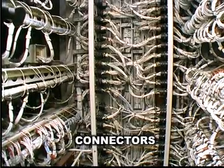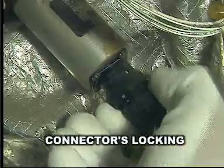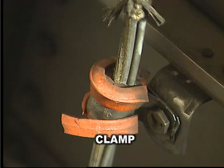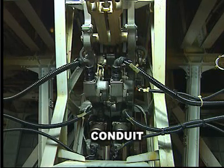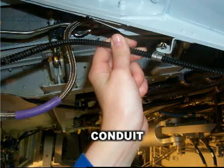The connectors, general aspect of their wiring, the connectors locking. For the clamps, do a check of the general aspect of the grommet. If, for example, the grommet is in the right position, if the wires inside the clamp are not touching the metallic part of the clamp. In this example, the grommet clamp is critical. General condition of the conduit, bent or broken.